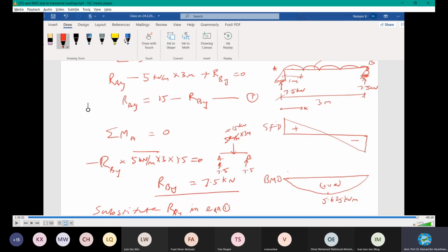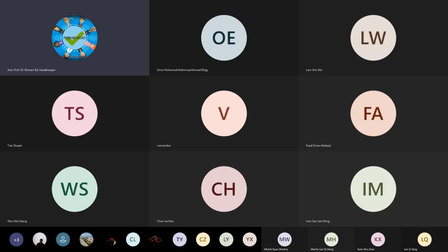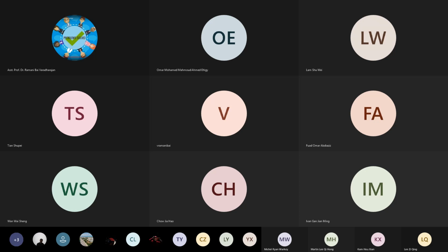Any question for today's class? I have posted for you. Yeah. For the calculation of the M max, how do you calculate the M max at x equal to 1.5 meter? I don't understand the calculation about the last part. 5 times 1.5 times 1.5 divided by 2.